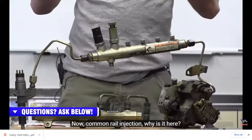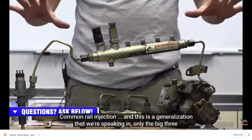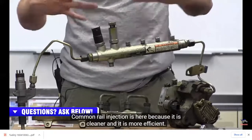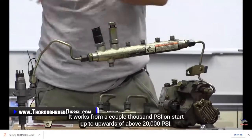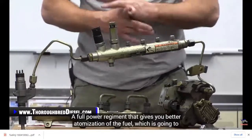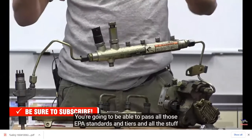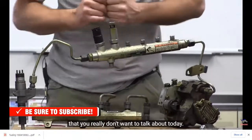Now, common rail injection, why is it here? This is a generalization, and we're speaking only of the big three light duty platforms. Common rail injection is here because it is cleaner and more efficient. It works from a couple thousand PSI on startup to upwards of 20,000 PSI at full power. It gives you better atomization of the fuel, which gives you a cleaner burn and a more efficient vehicle, and you're going to be able to pass all those EPA standards and tiers and all the stuff that you really don't want to talk about today.